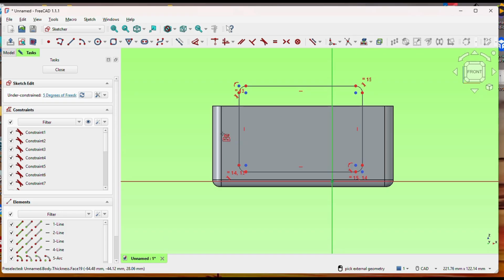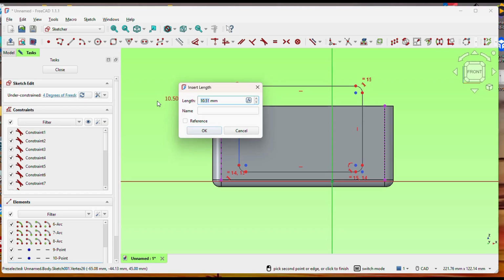Select this one. There. And there, that creates two reference lines for me. Get back out of this one. Right click, get out of that one. And then I want to just add dimensions to that. So let's go here, dimension from this line to that point. Let's make it about 14 millimeters.